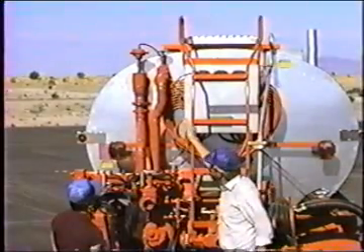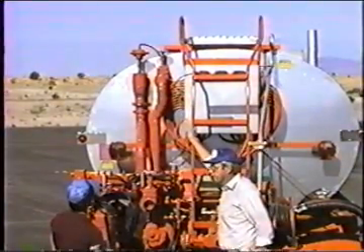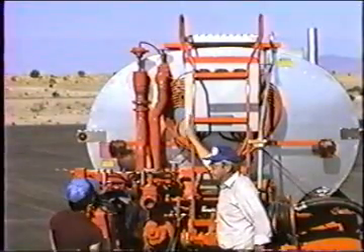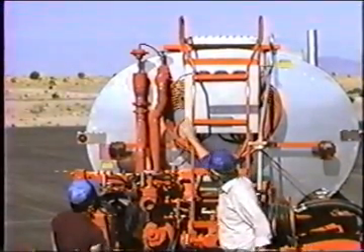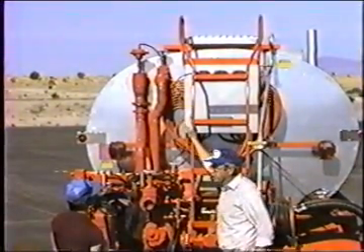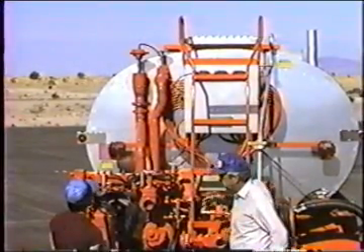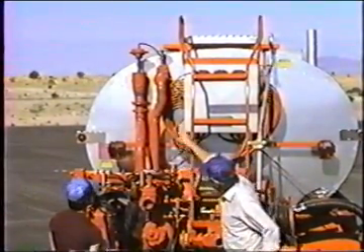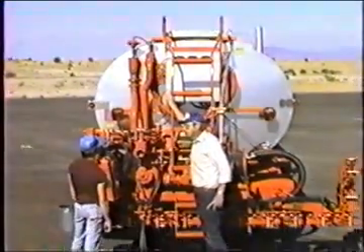The only time we ever open that valve is to circulate the tank. All other times that valve is closed, and it's very important that it is closed. If you were to leave that valve partially opened and you were trying to spray a specific amount of material on the road, some of the material could leak through that valve back into the tank.